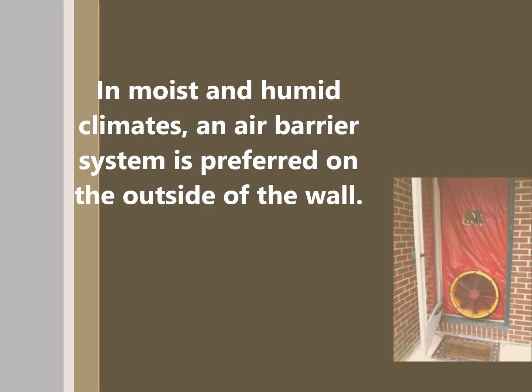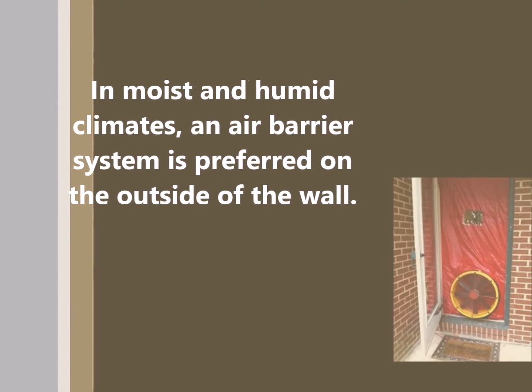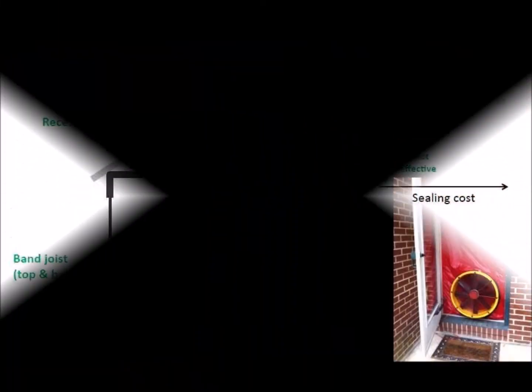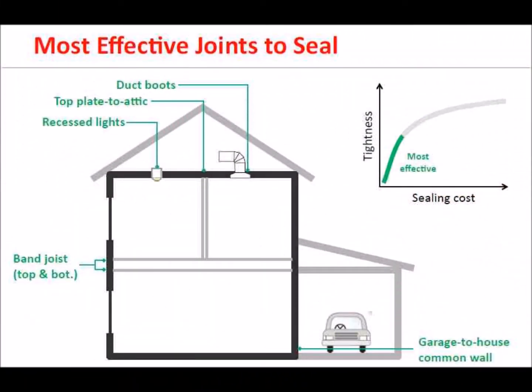Therefore, air sealing is important because air carries both moisture and energy, usually in the direction that's adverse to your client's wallet and comfort level. So let's look at air sealing. Air leaks can carry warm, moist air from a bathroom into a cool attic in the wintertime. Your client will probably already know that air can leak in and out of the house through small openings and around doors and windows, or even through a fireplace chimney.